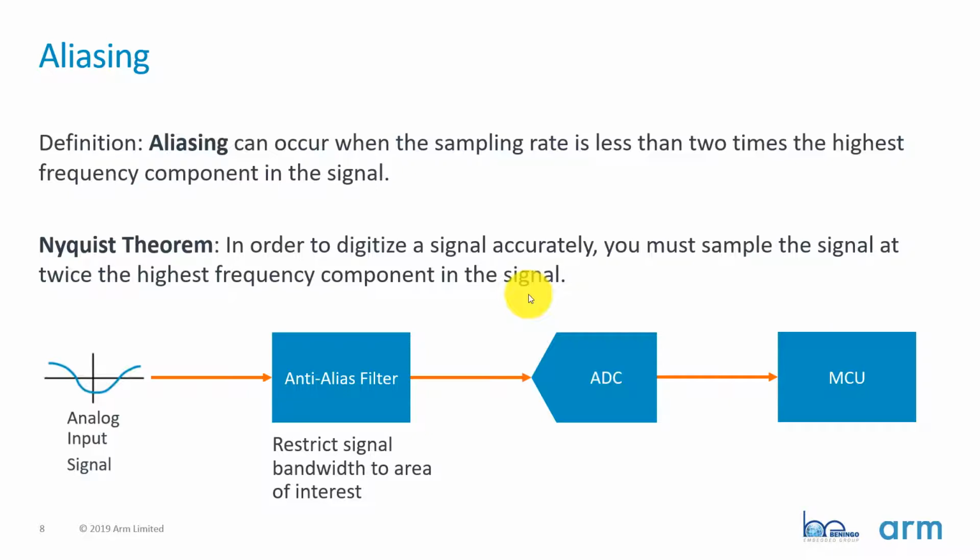And a great example of aliasing is if you've ever watched a television show where you see a car that's driving down the road. If you watch the wheels, you'll notice that as the car is driving, the wheels look like they're turning in the right direction. But over time, all of a sudden, the wheels will start changing direction, and sometimes they'll actually look like they're going backwards. And the reason for that is that the sample rate of the frames is not twice the maximum frequency of the actual spin of those wheels. So what happens is those wheels are actually being aliased in the frame, and you don't get an accurate representation of how those wheels are actually spinning in the real world. So that's a real simple example that you can check out whenever you're sitting there just watching TV. That's a real world example of how aliasing can affect how a signal looks when it's being digitized.